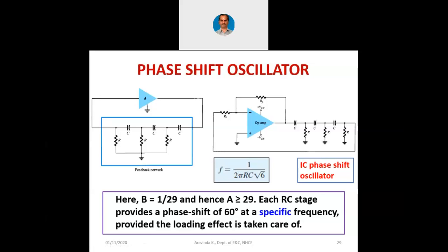On the other hand, you can assume C as 0.1 microfarad or 100 nanofarad. If you assume C as 0.1 microfarad, you can substitute the values of C and F, and then you can obtain the value of R also. That way, whenever we have two unknowns, one of the unknowns must be assumed with a particular value and then the other unknown's value can be calculated. In that way, we are going to proceed for designing the oscillator.